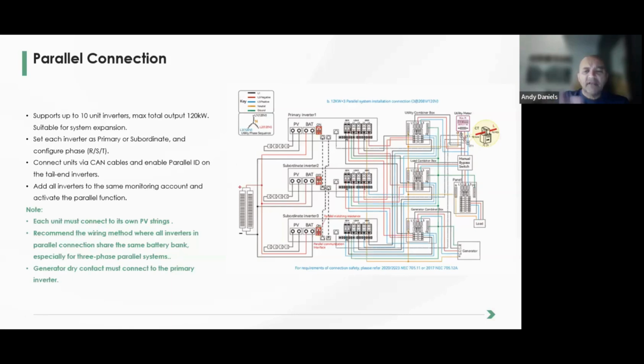And I think I explained this in a previous training session as well, that our inverters are grid following, right? So when they connect to the grid, especially in parallel like this, you've got to make sure that single phase parallel are connected to the same input, because they copy exactly what the grid is doing. So they will follow the grid voltage and the grid frequency for their output. It is only when the grid fails that the inverters will go to pure sine wave. And while they're in pure sine wave, they will then follow the output signal from the master. The master will control all of those things.